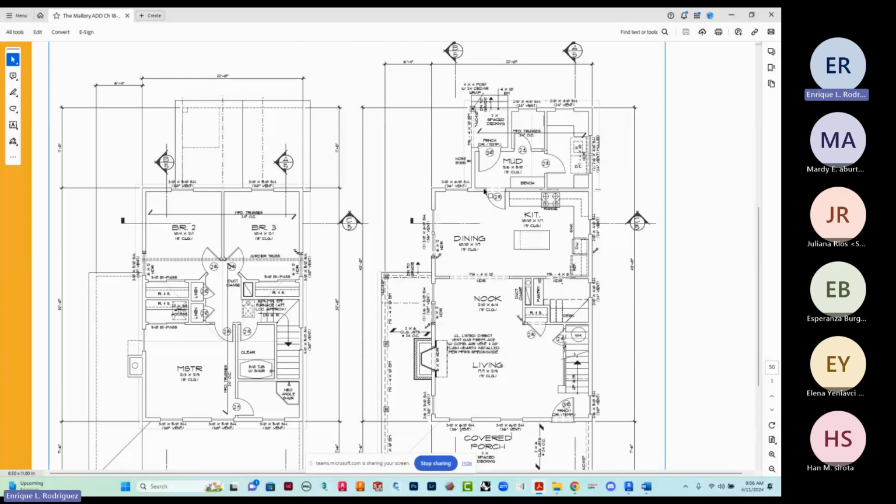So what I'm going to do is I can draw either a guideline from here to here, or I can offset this same wall up the 5 feet, but I then need to add the width of the wall to it. So I would offset it 5'6".